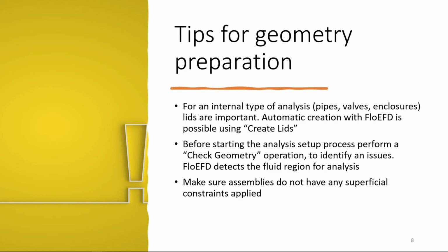Some other tips for the geometry preparation are that if you're doing an internal type of flow analysis, just make sure that all your ends are closed. So make sure you create the lids. In case you forget to create the lids when performing an internal analysis, FloEFD has the capability to automatically create a lid, which we will take a look at in the actual demonstration.